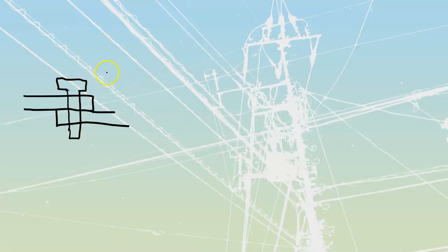Because in a lot of cases, you're going to have these bus bars that are going to be dissimilar metals, aluminum usually, and then you're going to have this, which is going to be a steel type of bolt. And because they're going to expand at different rates, that means that this joint is going to get tighter and looser. The way that we deal with that is that we are going to place on either side what's called a conical washer.